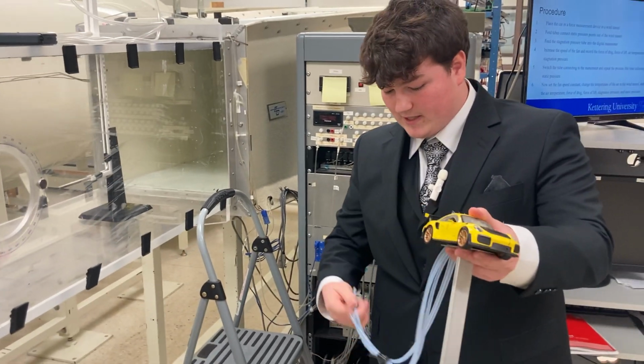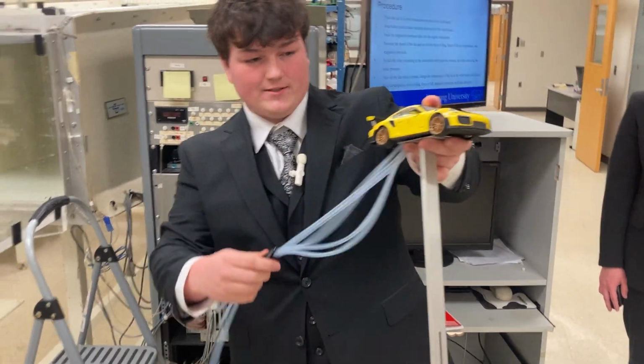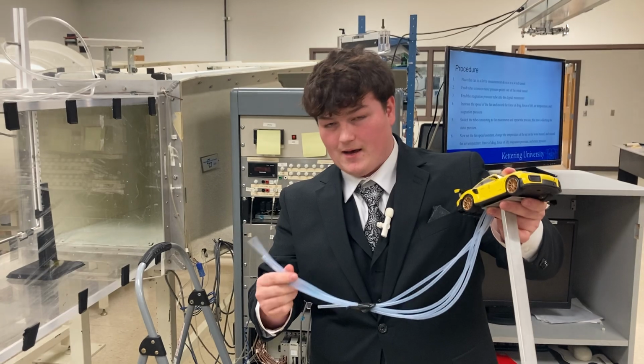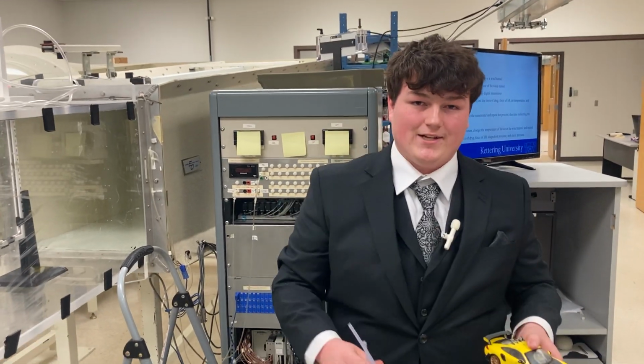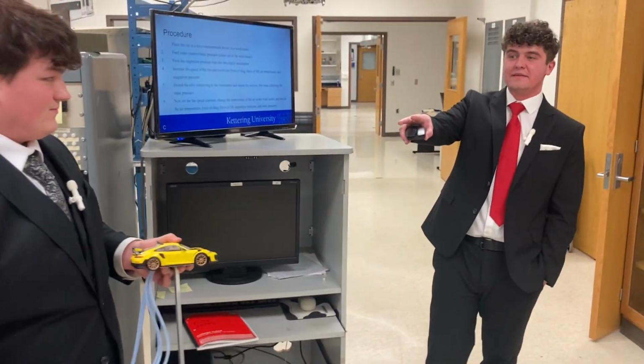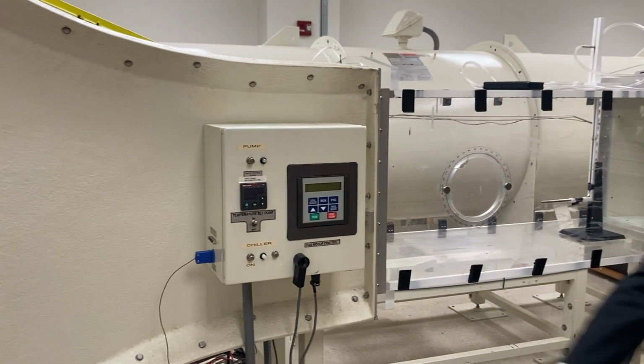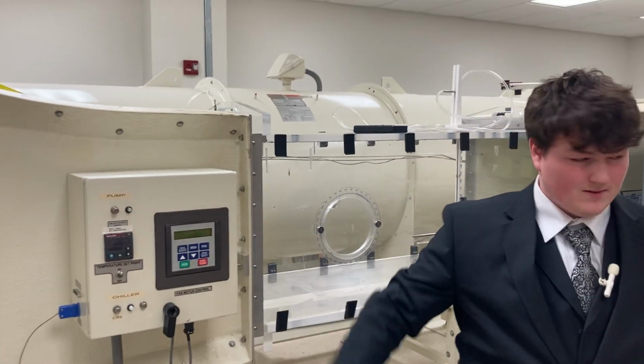With the digital manometer, we had various readings. We had all of these labeled and we put the manometer on them to get our different stagnation and static pressure readings. Additionally, we changed the speed at which the fan was operating and the temperature of the air going through the tunnel to measure our different properties and get us some results.